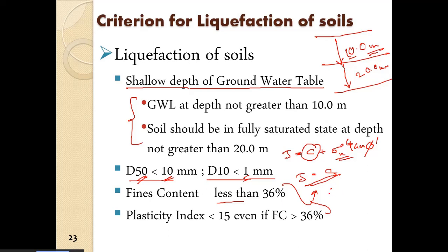There may be deformation, but the flow liquefaction state may not be totally achieved, and the soil may stabilize. This remaining shear strength, the cohesion in the soil, will help in stabilizing the soil and in reversing the chances of liquefaction.